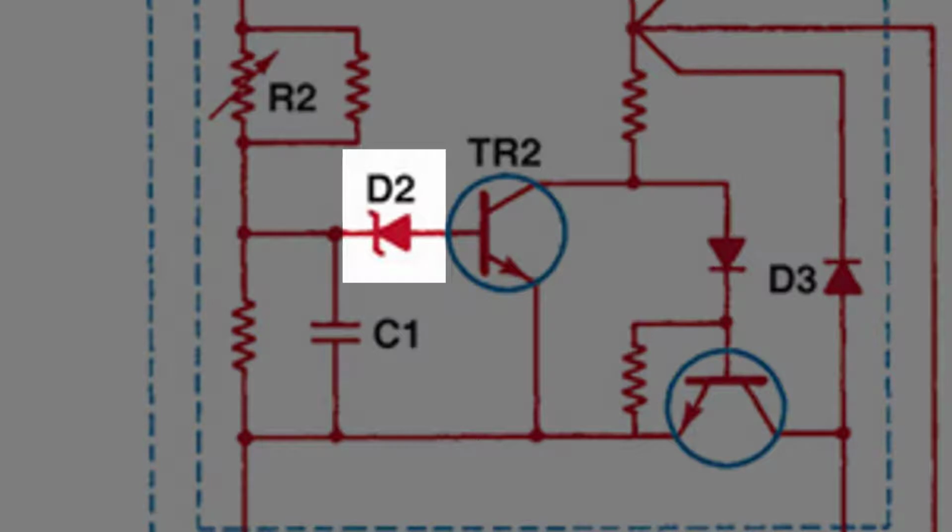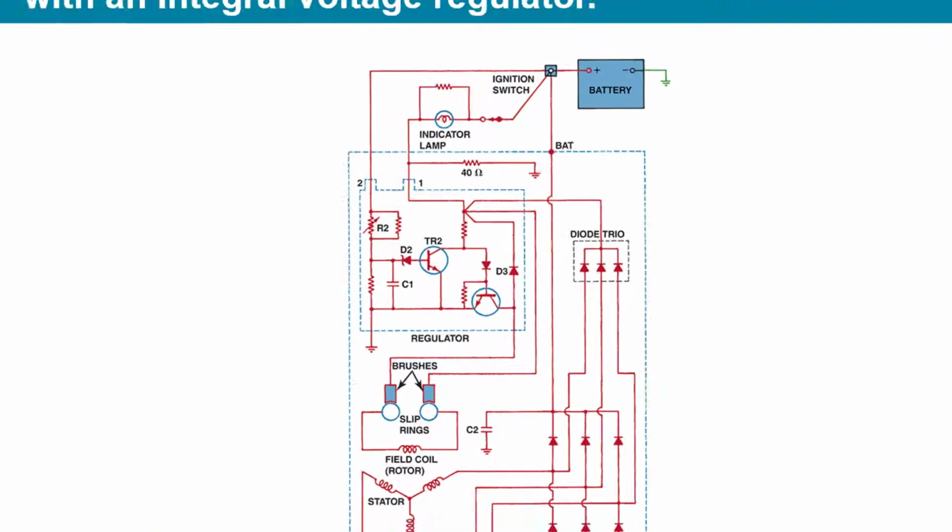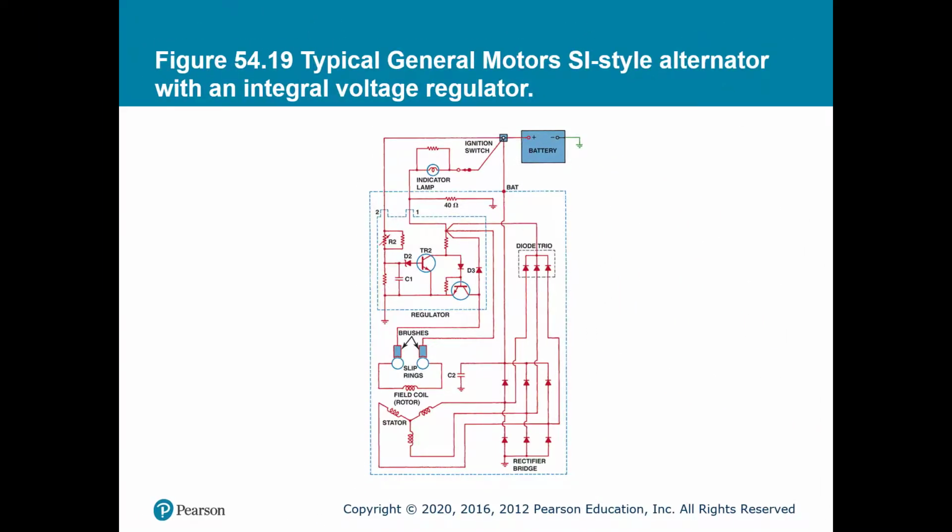And that diode, as I said before, will allow current to flow once a certain voltage parameter is reached, which essentially gives this system the ability to function. So it's kind of the brains or the traffic cop behind whether the alternator provides voltage or cycles on or cycles off.